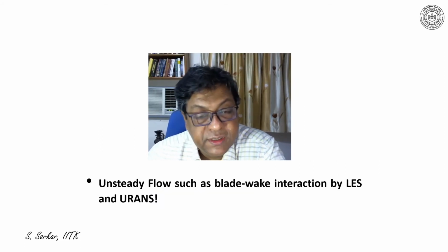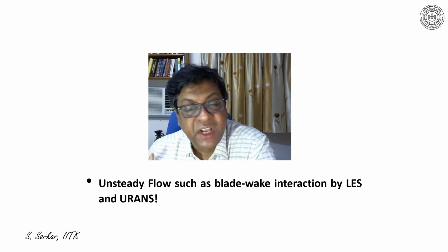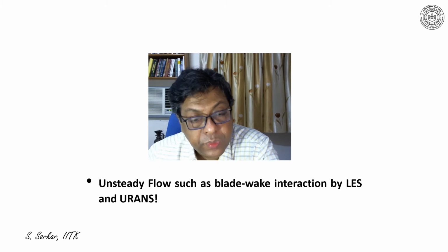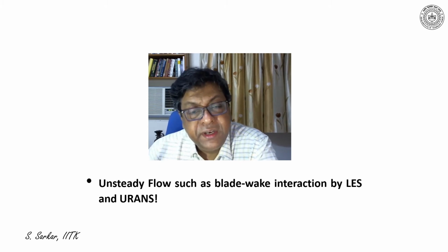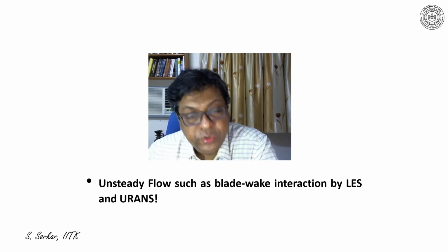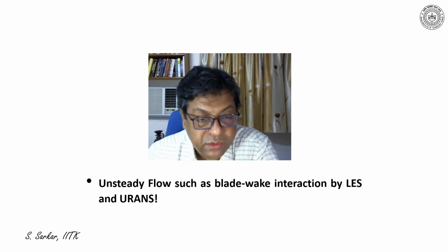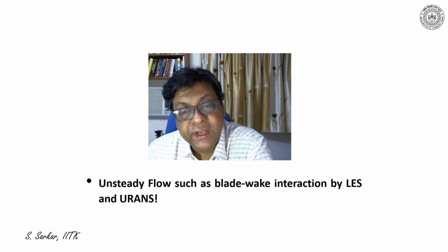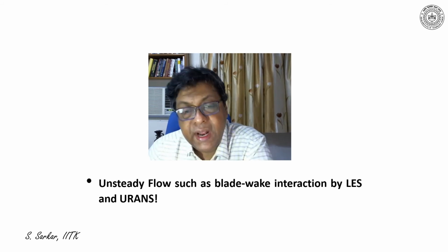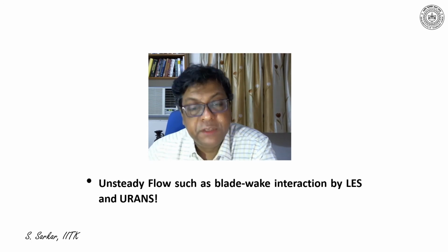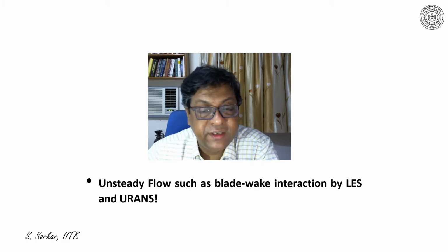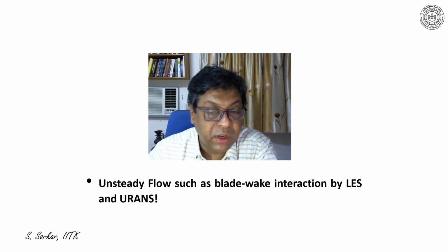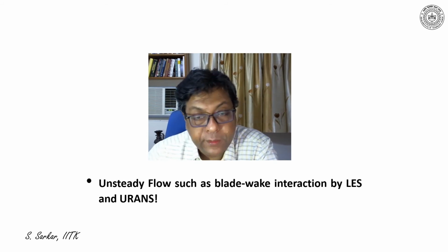Prediction of unsteady flows in turbomachinery is very challenging, particularly when Reynolds number and turbulence intensity are high. I would present here a case where we have resolved the blade-wake interaction for a low-pressure turbine blade. Here, ALES is needed to resolve the flow field. And in another case, I'll show the unsteady flow which has developed due to the rotation of a vertical axis wind turbine. Here, URANS along with some appropriate turbulence model is successful in predicting the flows.